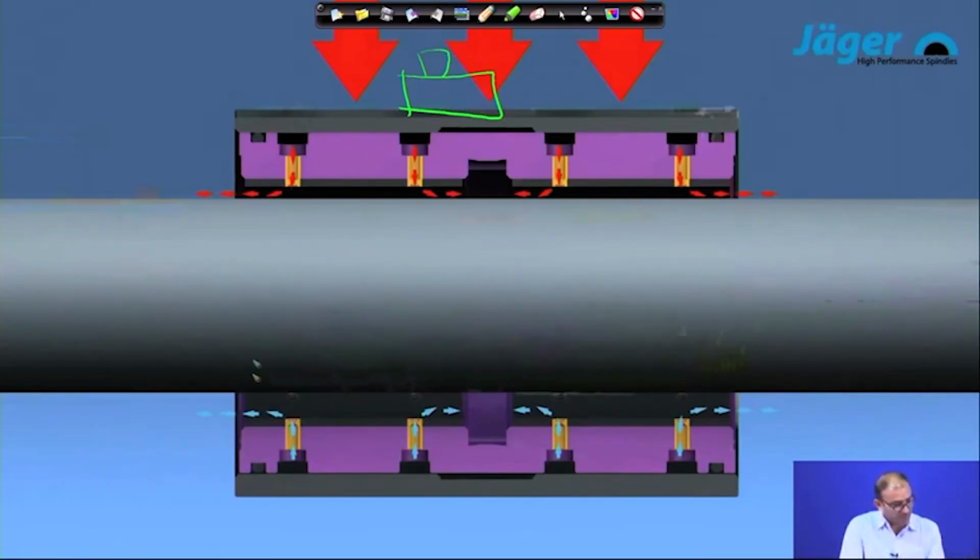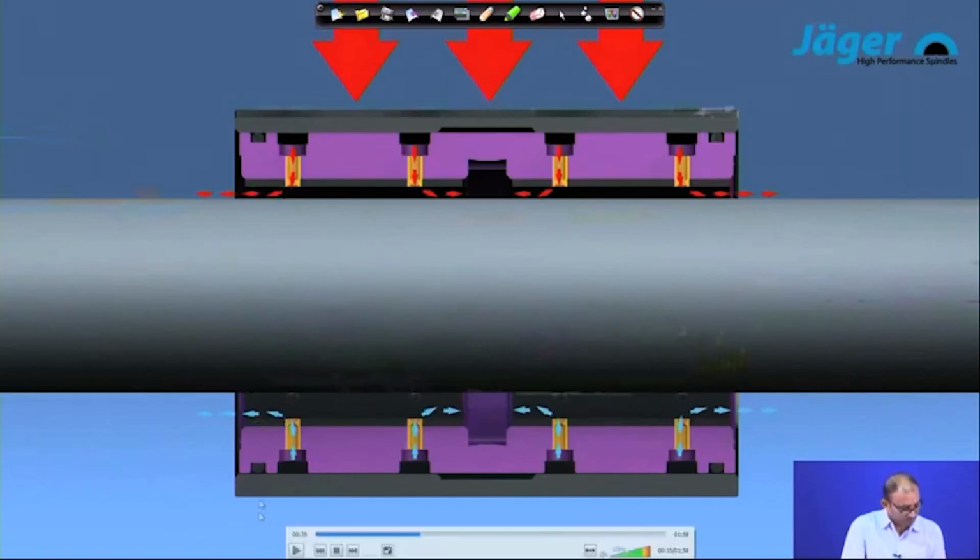Because of that what has happened is that earlier it was a balanced force, right, force at this location and this location both were the same, but when you are putting this thing down, the space available here is less. If the space is less your pressure is more, and here the space is more, so your pressure is less. So, once this happens, this particular bearing will adjust itself, you do not need to see how it is going to happen.